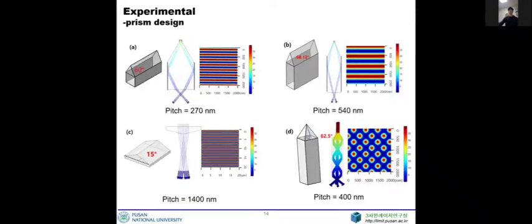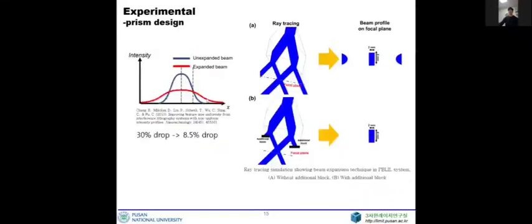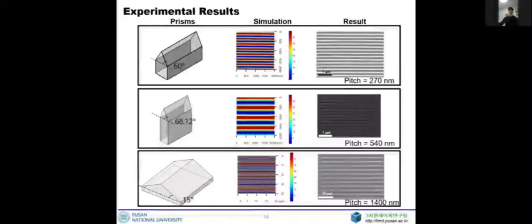This page shows various prisms used in experiments. Prism shape defines the pattern, and it is shown in this page like this. Also, the prism cuts the incident laser beam for more uniform intensity distribution. Changing the prism, the laser beam was exposed on the silicon substrate.